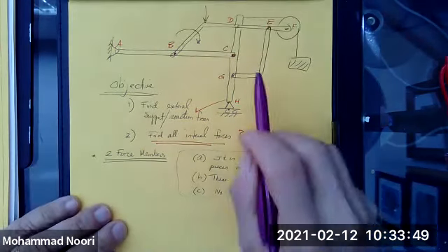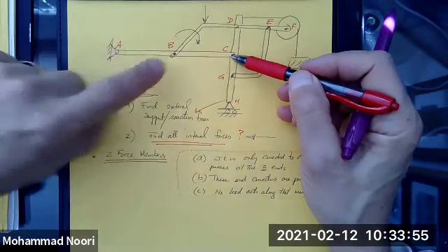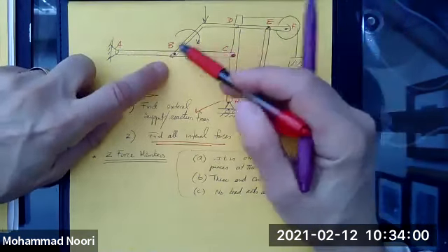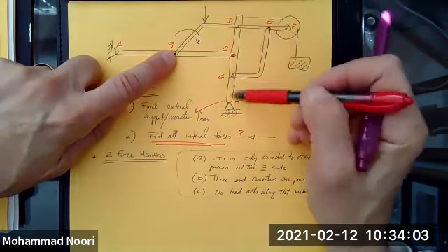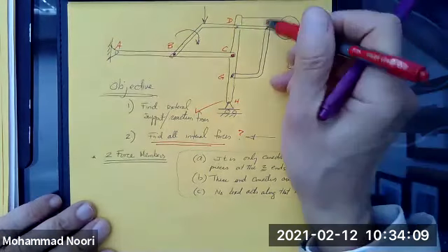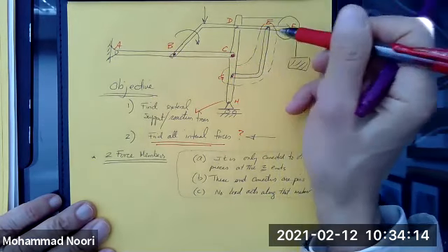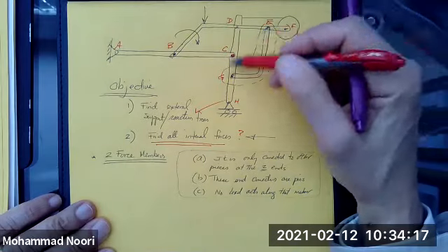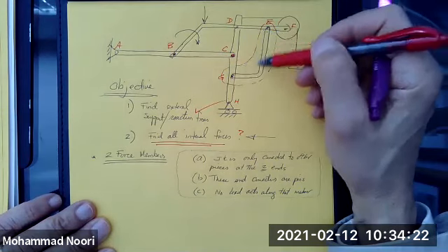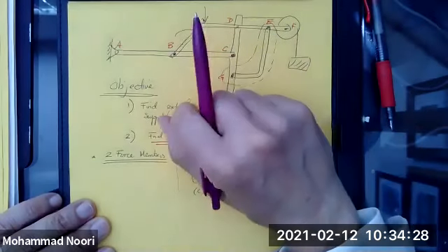Do you see a two-force member in this structure? Let's look closely. This has connection at the two ends, but also another member is connecting to it. And also, not only that, there's another load coming here. Same thing here, same thing here, same thing with this. But you look at this member and you say, wait a minute, this member is only connected at the two ends to the rest of the structure. These two ends are pins, and there is no load in contrast to all the others acting on the structure. So this is a two-force member.